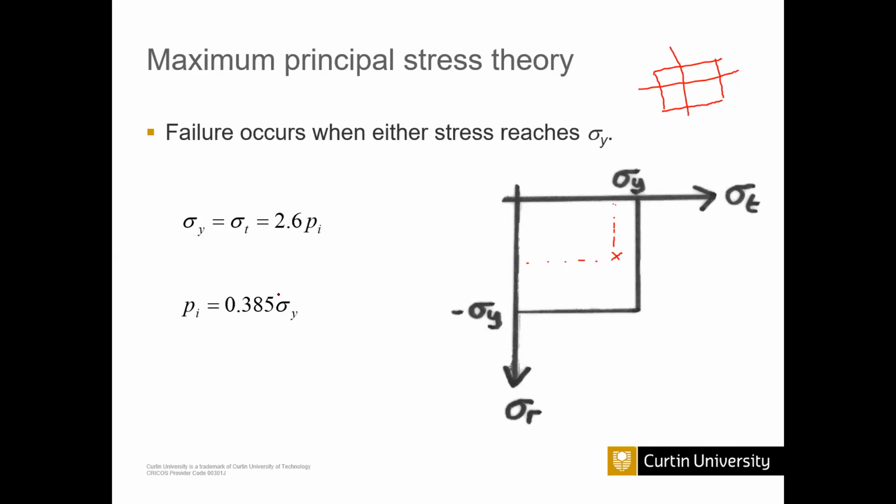So with this relationship, if you apply internal pressure 385, that material will be somewhere here, that cylinder inner surface somewhere here. So if we apply 386 megapascal pressure, that particular material will fail. So I hope you understand that one.